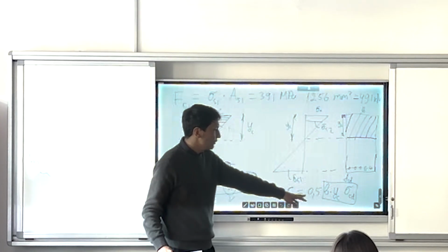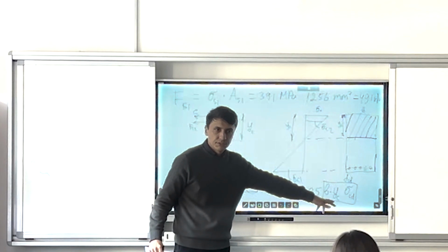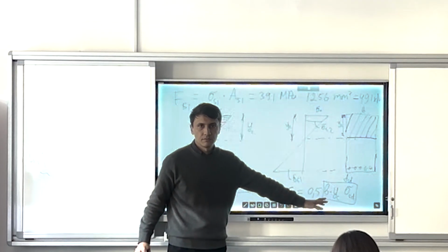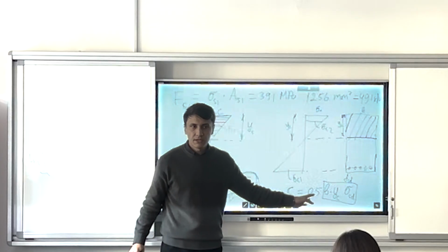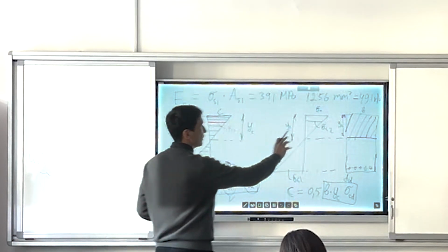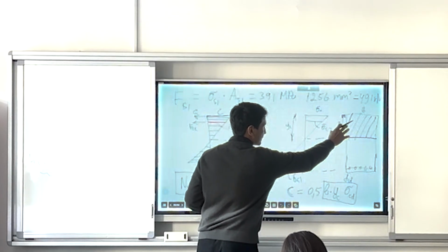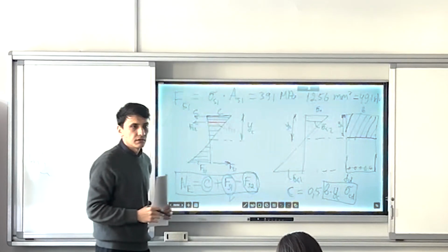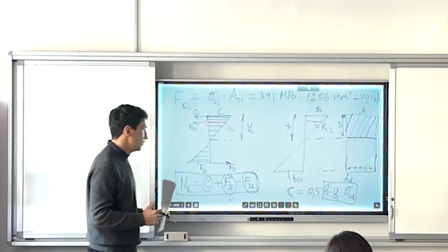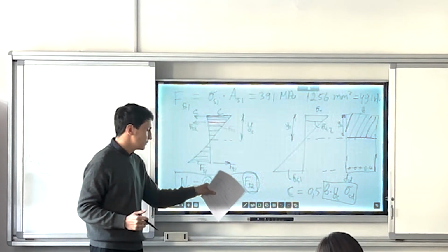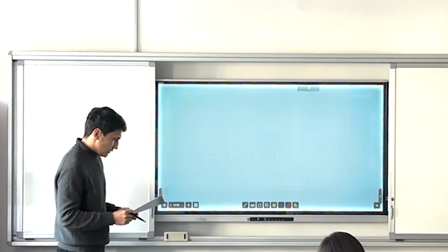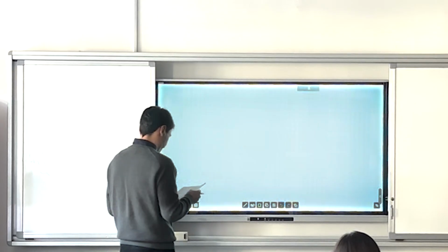Now you know what this means: these three terms give us the force from the concrete. The 0.5 is an assumption that only half of the area of the compressive part gives us the compressive force. So now we know all three terms of this equation. Let's write this.